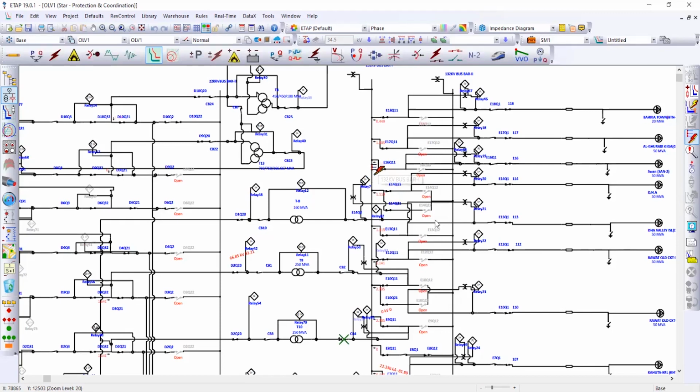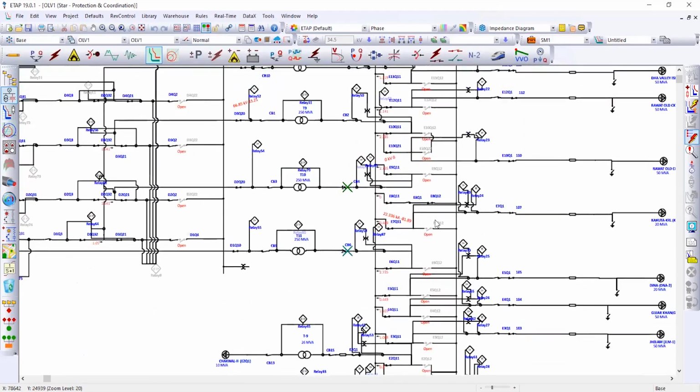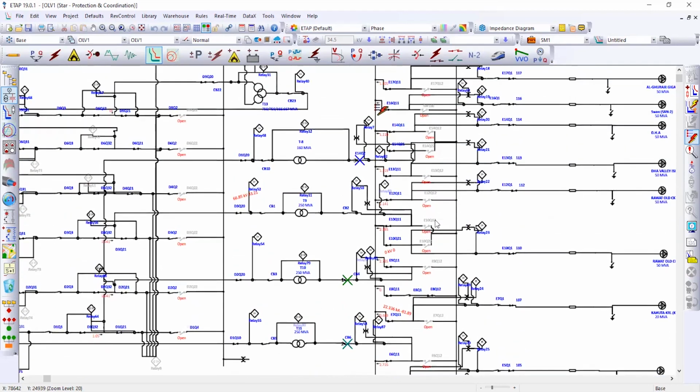As could be seen here, on introducing fault on our main bus bar, the respective circuit breaker would be tripped, and then we would shift our load to our transfer bus bar, and then our operation could be started normally.